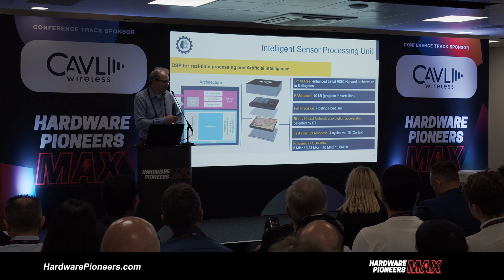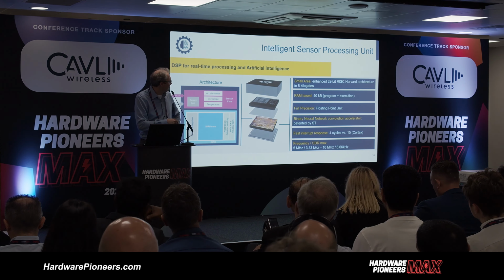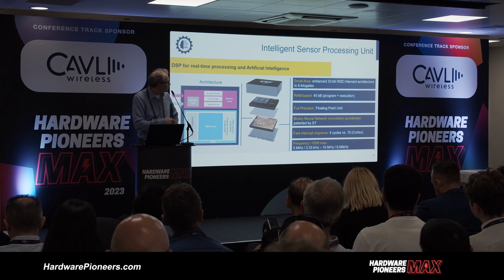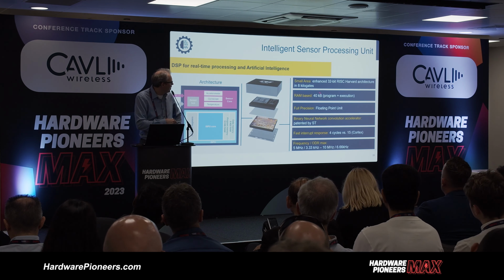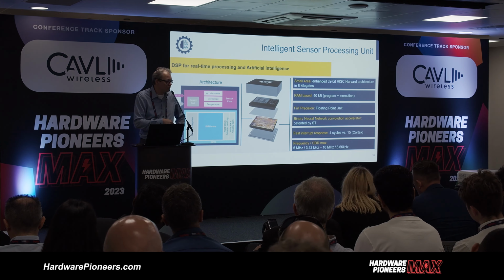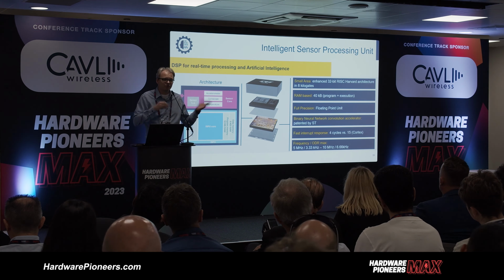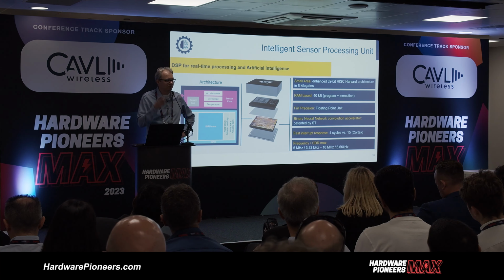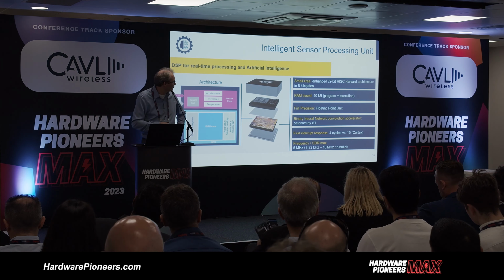Some more details of the component itself: we actually have a 32-bit RISC microcontroller inside. It's RAM-based, so we have roughly 40K RAM for program and execution. So not to run very complex image processing algorithms, but especially just to check the accelerometer plus gyro data at low power.